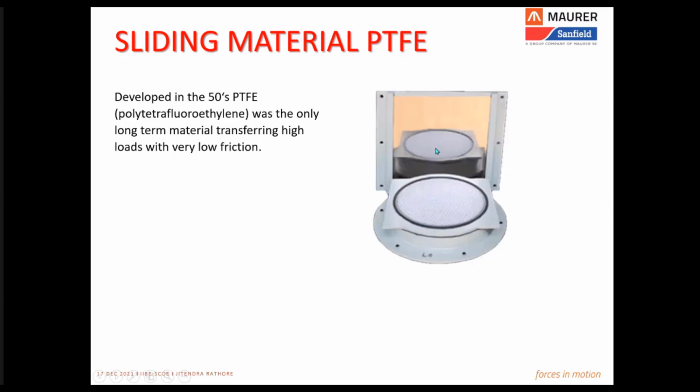steel sheet. Since the bearing has to do a continuous movement in the bridge, and since there cannot be an ideal interface where there is no friction, there will be a certain amount of friction. So what does this friction result in? It results in the wear and abrasion of the sliding material.